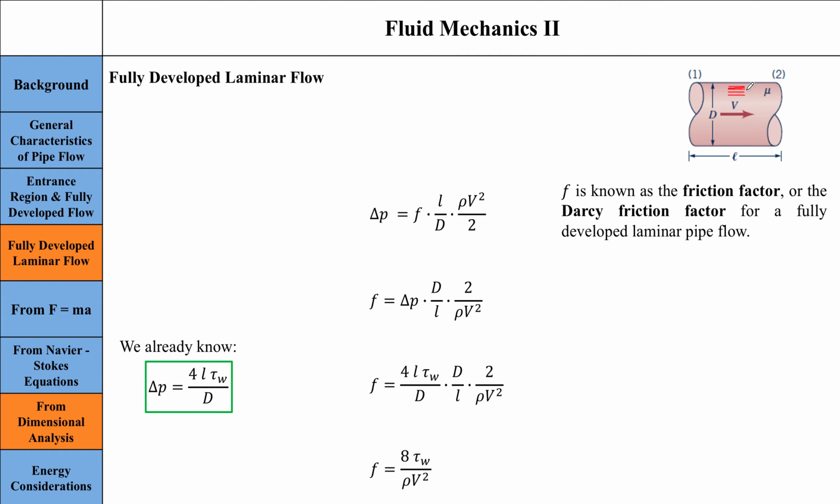And these layers of fluid, because they have a varying velocity, are causing a shear stress, which is represented by tau W here. And because of these viscous forces, we have friction losses. Friction develops, and because of that, energy losses in the pipe start taking place.